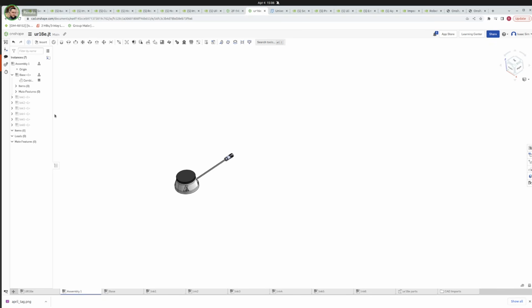It moves the pieces and not the assembly, because that's how Onshape does things. So let's hack it away. Let's create groups for every individual assembly so that when we move it, it moves the entire assembly out.